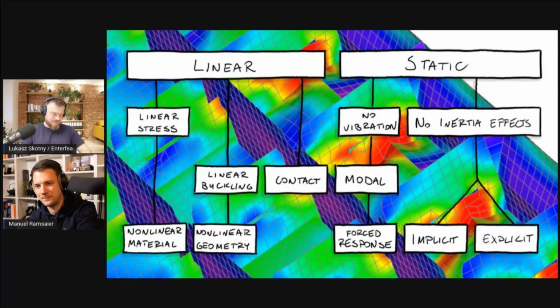And it just happens like that. Although the problem is that the fact that you run explicit analysis doesn't necessarily mean that the outcomes have any sense. You need to be extra careful what you've got because I saw that too. Overdo mass scaling or something like that, you can get to very weird places very quickly.